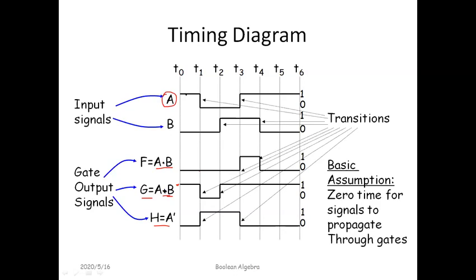Okay, so if we look at signal A, from 0 to 1, it's high, meaning the output will be low from 0 to 1. Then at 1, signal A transitions from high to low. The moment signal A transitions from high to low, the output will transition from low to high. Then from 1 to 3, signal A is low, and the output from 1 to 3 is high.